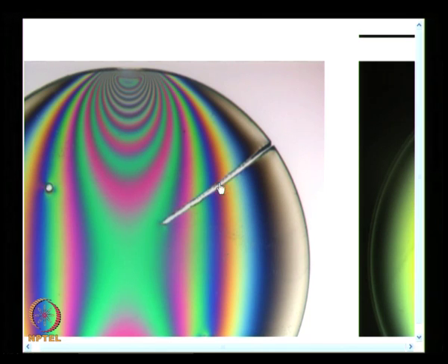And similarly, if I do the slicing properly, suppose I make another cut here, I will have a slice like this. So, that slice will retain the original stresses that have been locked. So, when I do a machining process, I must take sufficient care that I do not introduce any kind of machining stresses, and you have to also have a coolant, so as to take away the heat, and you use a single point cutting tool. There are many restrictions on how you do it, and you need a mechanic trained to handle these kinds of problems. They will use a high speed, single point tool, and then minimize generation of machining stresses.